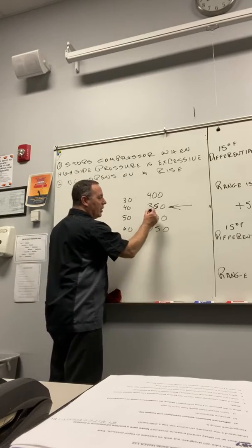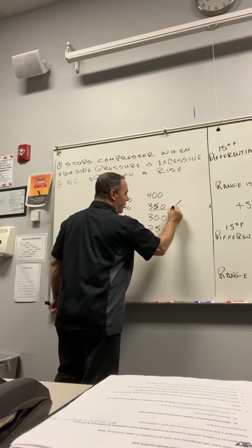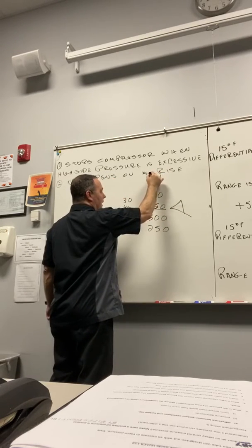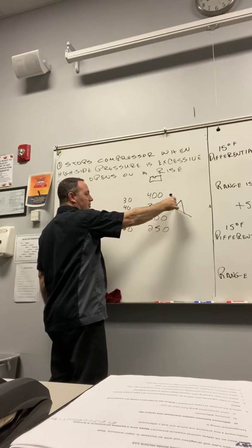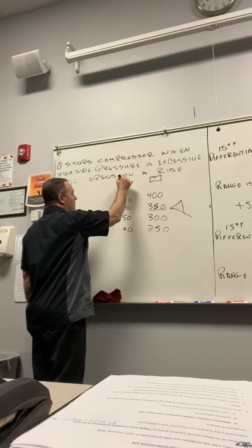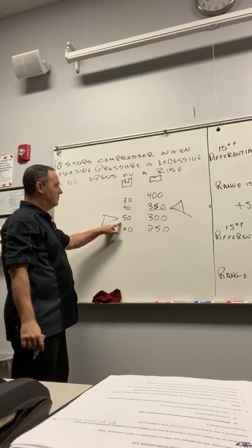So if I wanted to cut out at 350, I'll move this arrow here with the screw at the top. They'll have a screw, and you can actually turn that, and this will move. And then I'll set my differential to 50.